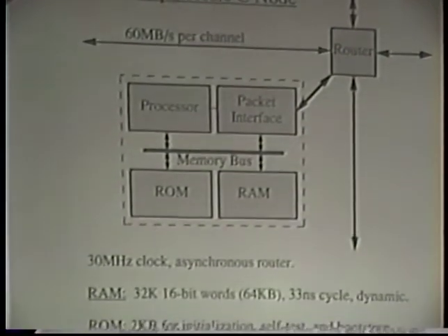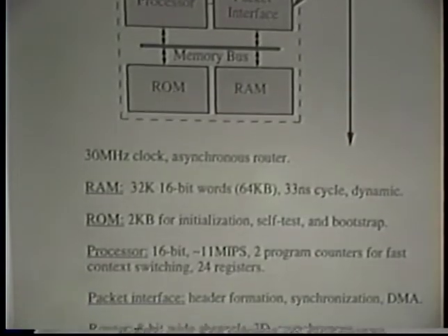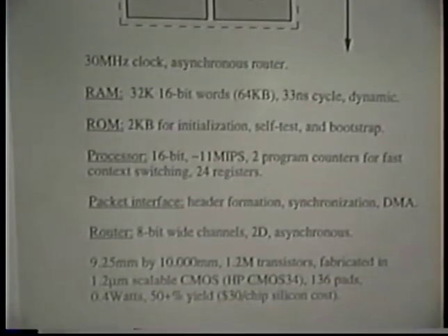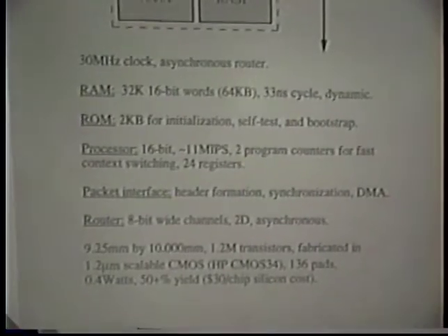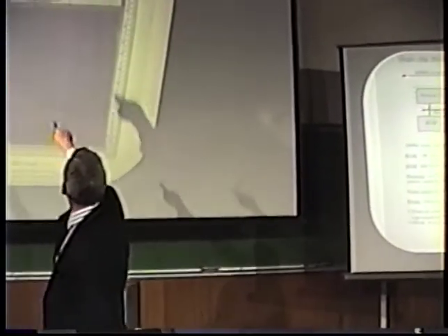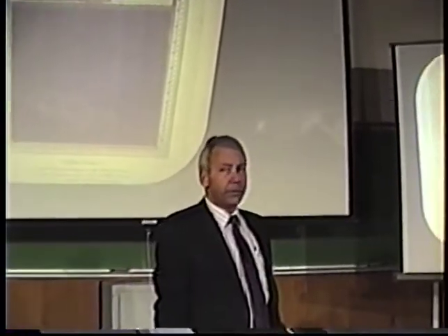There is a statistic that's kind of interesting to me. 61% of this chip area is the primary read-write memory. More than a quarter of the chip is devoted to communication. That is the pad frame, the connections to the outside world around the edge, the router, and the packet interface. The processor is only about 3% of the chip area.